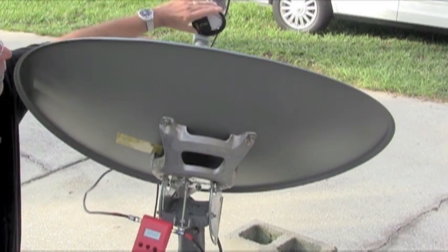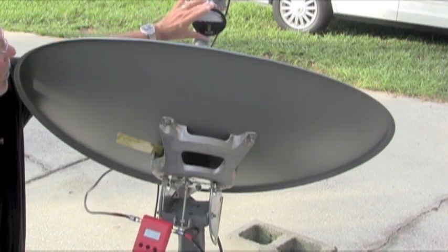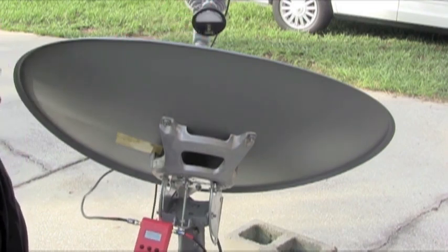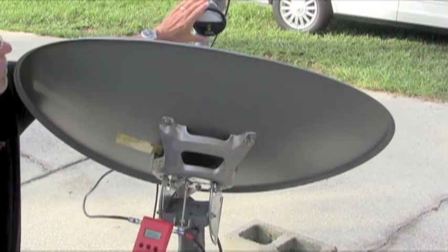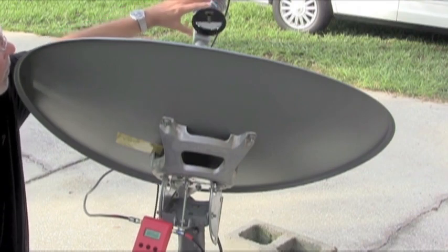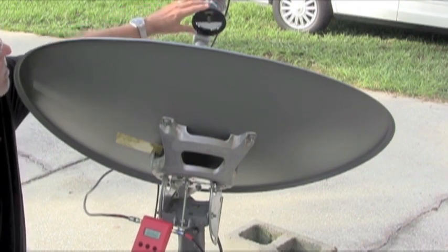So now we're going to put the opening to the top and we're going to take a reading. And here we can see the signal looks about the same as it did on azimuth. So now we need to check it at 180 degrees. So we have about a 95. And check at 180 degrees and see if we can get the two to be within 5 points of each other.